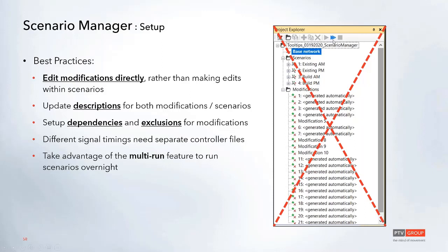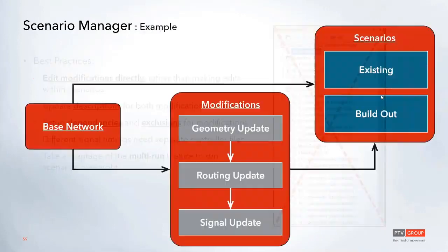And then finally, using this multi-run feature up here at the top is a great way, if you've finished creating some initial set of runs or if you wanted to do a final set, to run all of your scenarios. It'll go through and finish running all of the seeds for run 1, and once that's finished, it'll kick down and go to 2 and 3 and so on. So it's a great feature to use if you just wanted to run these overnight and then check on your results in the morning.